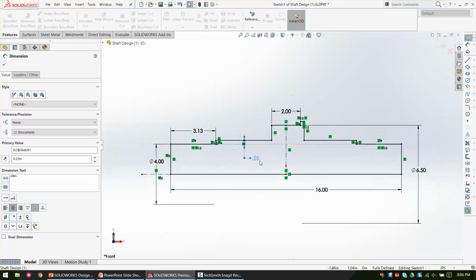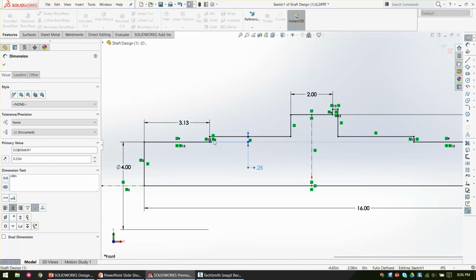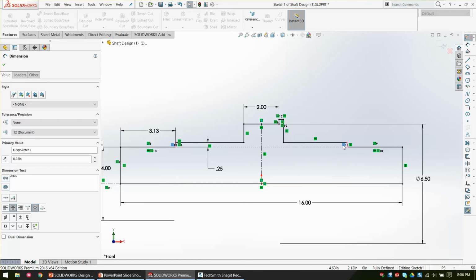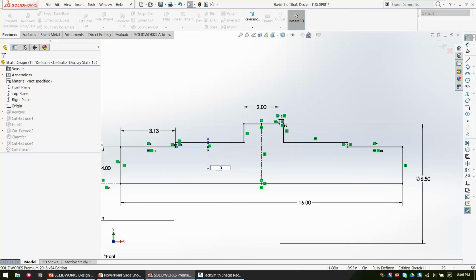So in this instance, I define a 1/4 inch once, and I've got retention ledge, retention ledge, retention ledge. And I can slip on a couple bearings and a sprocket, and we're all good. If that's a problem, it needs to get bigger. All of those can get bigger. Nothing else changes. So good design intent. I intend to have a consistent lip to retain all of the circular bearings and sprockets and stuff I put on the shaft. And I can drive that with a single dimension with no other geometry changing at all. My stack-ups are the same, my assemblies are the same, everything's identical.